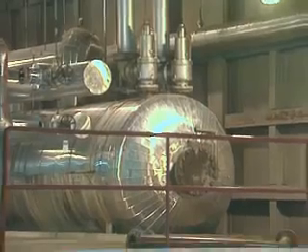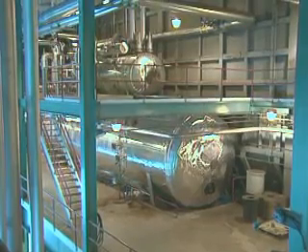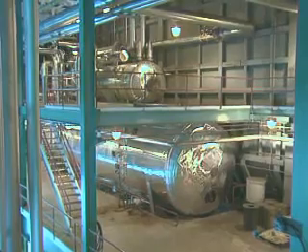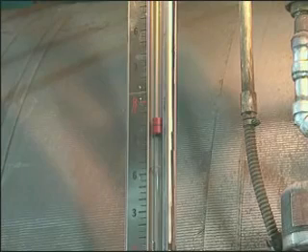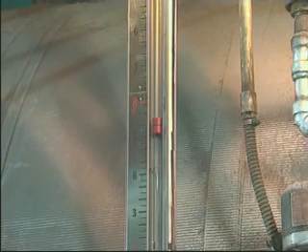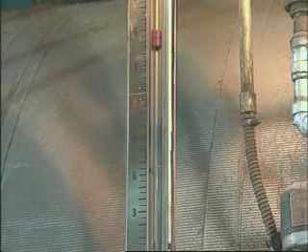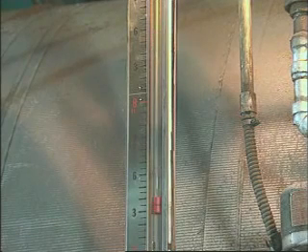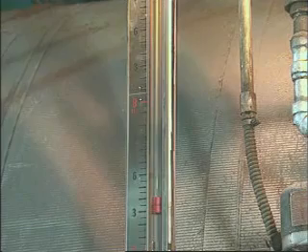The deaerator, which is an open heater, and the hot surge or deaerator storage tank that's associated with the deaerator must also be monitored when a condensate and feed water system is in operation. Check the level of water in the hot surge tank. There's usually a level sight glass on the tank that's used for this purpose. If the level is too high, water could flow into the deaerator and, in extreme cases, even into the extraction system piping. If the level is too low, the net positive suction head for the pumps downstream of the tank is reduced. As a result, the pumps could be damaged.